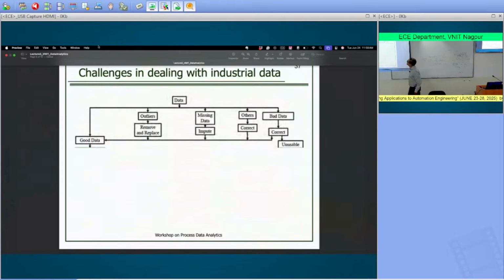There are several challenges with industrial data. There are various reasons why you want to pre-process your data. For instance, there are often outliers. What are outliers? Outliers are measurements that don't belong to your measurement, right? Whatever that variable is. So let's say you expect this variable to stay in a certain range, an upper bound and a lower bound, and you suddenly get a measurement over there, then that is likely an outlier, not an artifact of your process, right? Then you have to identify all of those and replace them. So you can remove this and perhaps use linear interpolation here, find a corresponding data point that stays within the bounds in which that variable is expected to stay.